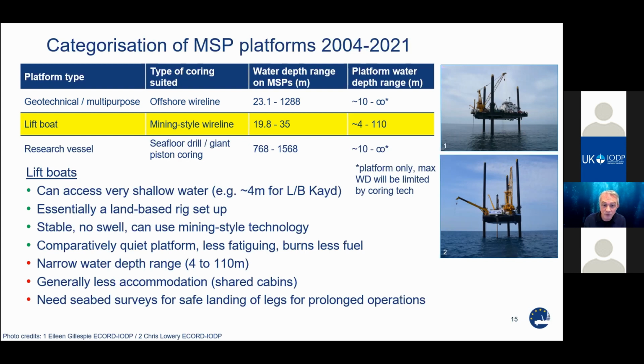These elevating platforms require seabed site surveys, basically geophysics and cone penetrometer tests, and that's to ensure that the ground conditions are suitable for prolonged occupation, so that extra survey requirement adds extra logistics and costs. And the final point on lift boats is that these vessels cannot easily cross oceans. They are generally only available near market areas.